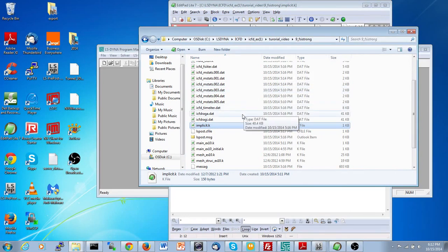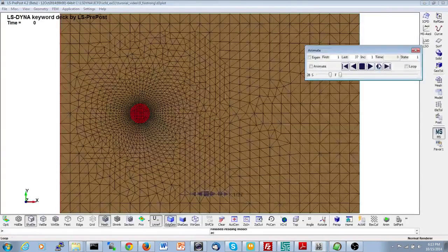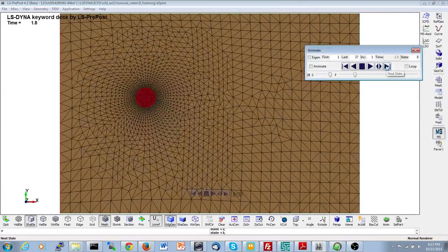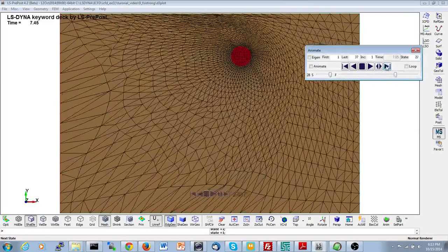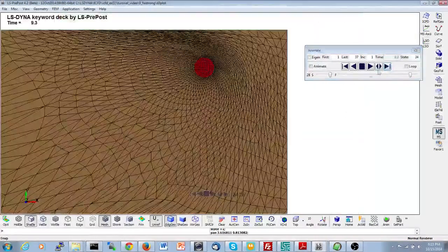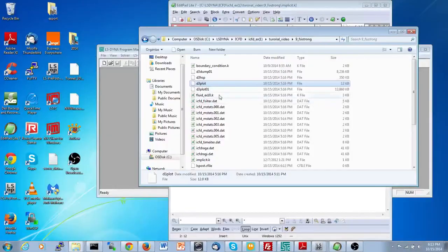Basically, if you use the explicit solid mechanics solver, you're automatically going to trigger loose coupling, and if you use the implicit solid mechanics solver, you will automatically trigger strong coupling, because there is no other way. There's no way to do otherwise. So now, after triggering strong coupling, if I start running the case, I will see now that it behaves in a much better way, and it has a more consistent behavior. Okay.